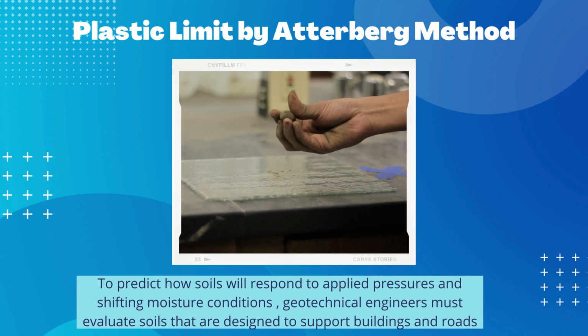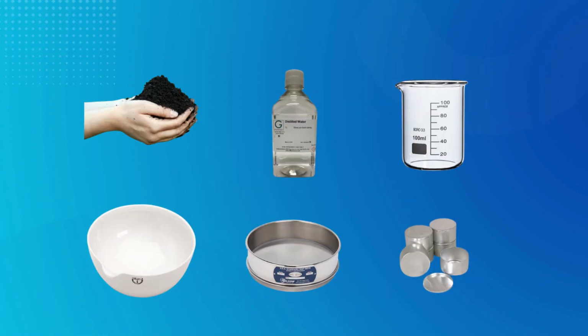The test results, or related indices, are used to predict how soil layers, dikes, and roads will behave, as well as to design the foundation of buildings. The measurements also identify expansive soils and forecast settlement by determining soil permeability and shear strength.